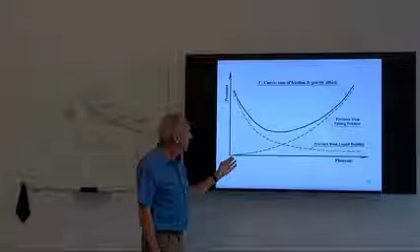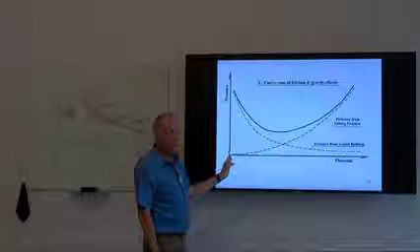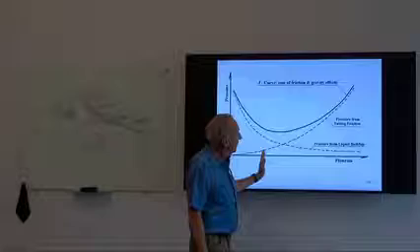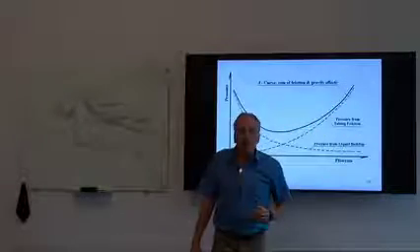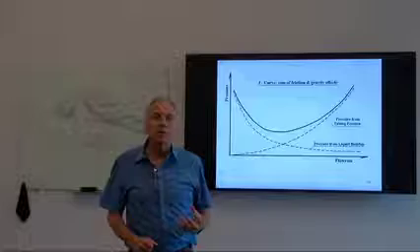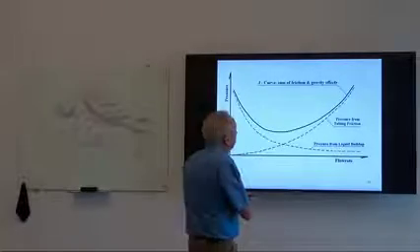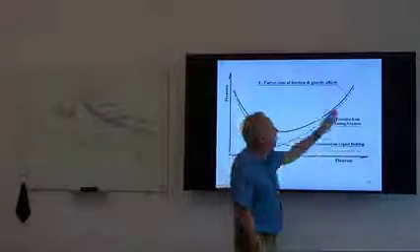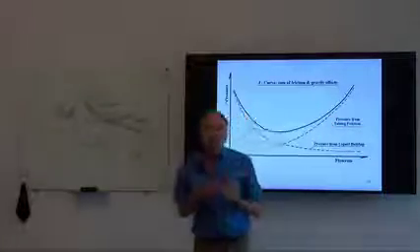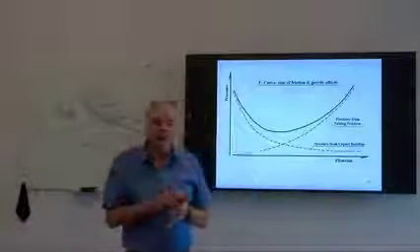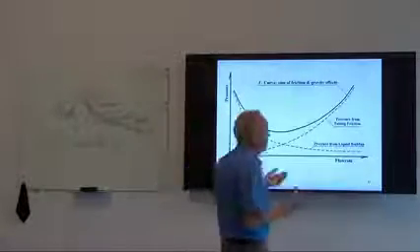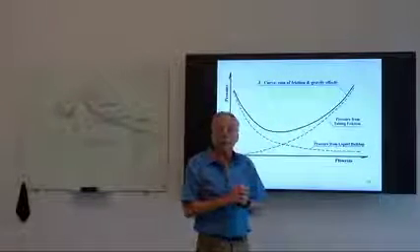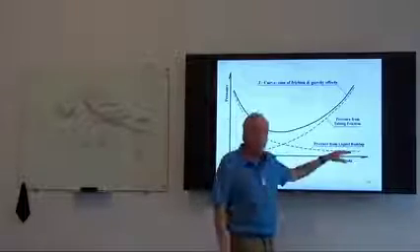If we think about friction for just one moment, if the flow rate is very low, there's very little or no friction. As that flow rate increases, it makes sense that our friction would also increase. With liquid buildup at a very high flow rate, friction is high, keeping the flow very turbulent, very highly mixed. The pressure from accumulated liquid, or at least from the amount of liquid held up in the tubing stream, is actually quite low.